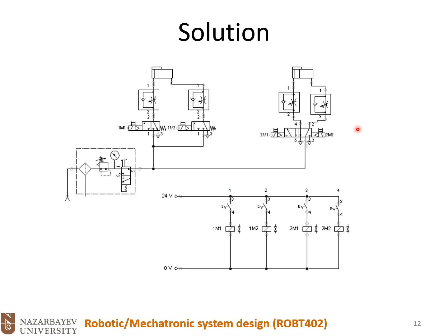And later, as an exercise, you could start to simulate the pneumatic circuits of other stations. Of course, I will give you the schematic diagram of stations, and then I will expect you to replicate that pneumatic diagram of those stations in Festo FluidSim.